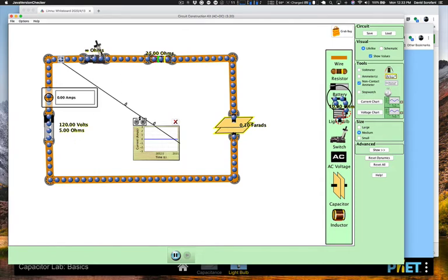in the circuit. And when I close this switch, watch the value on this ammeter over here at the instant that I close it. Here we go. Watch. And you can see it's in the high 3s. It's actually 4, as you would expect. Again, it's 120 volt potential difference of the battery. 30 ohms of resistance, 120 divided by 30 is 4 amps.